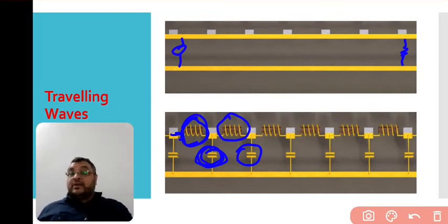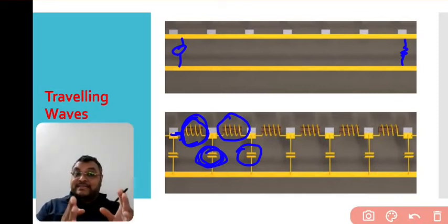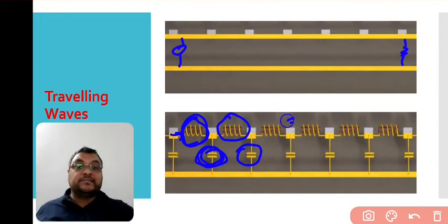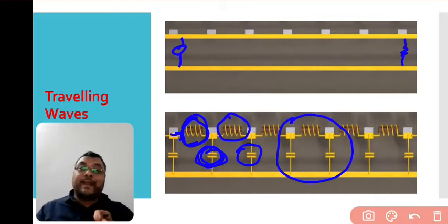So it is not the case that when we switch on the supply, power immediately or instantaneously moves forward to the load, because there is an inherent property of the transmission line: some inductance and capacitance is always present, and we do not deliberately connect those components in the transmission line, they are its inherent properties. So it takes some time, some delay, when we switch on the supply and the supply travels toward the load.